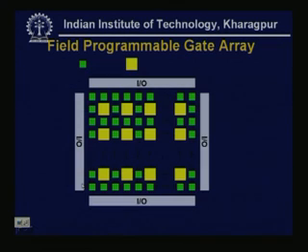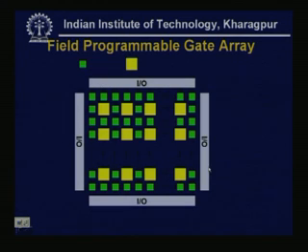Now, another is the field programmable gate array, and nowadays this is the state of the art of VLSI design. As I mentioned, these PLD devices are one of the basic building blocks of the ICs now, as a large volume of design can be fabricated on a piece of silicon. So, this field programmable gate array is nowadays an alternate to the normal CMOS ASIC. Now, we see the structure. This is similar to the CPLD.